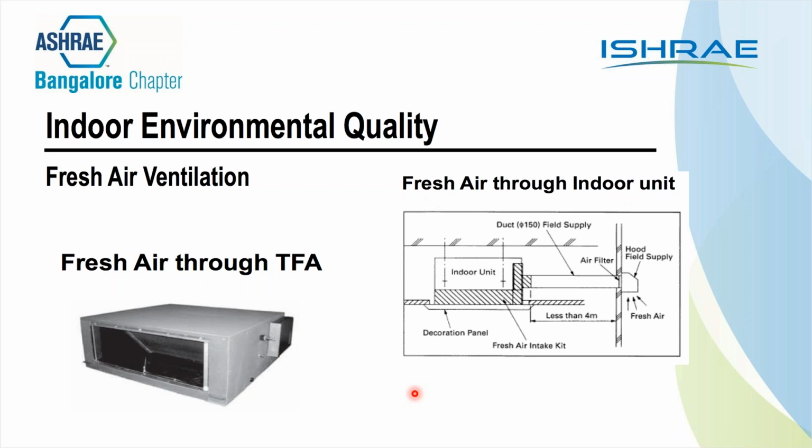You can couple it with indoor units. Let us say in 10 tons, you can have 6 tons of indoor units, like a cassette or high wall, where you can consider diversity. But if you are having a treated fresh air unit for your fan coil unit, then you cannot consider any diversity for that particular unit.